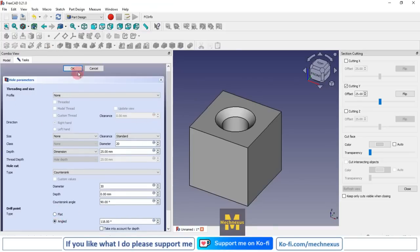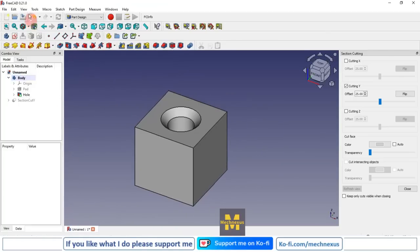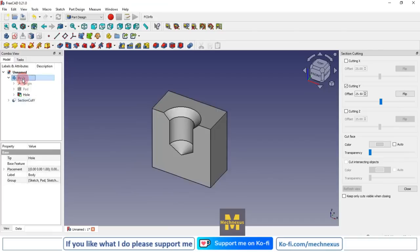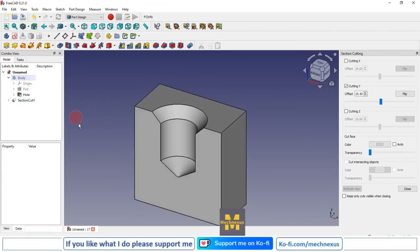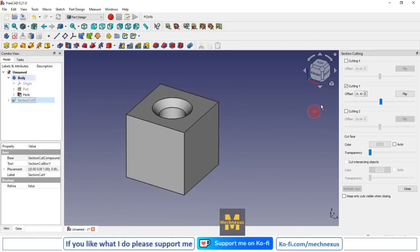And now we will click on OK, and we will take the sections. So go to the view, persistent section view, and turn it on the body. So you can see that we have created the countersink hole.